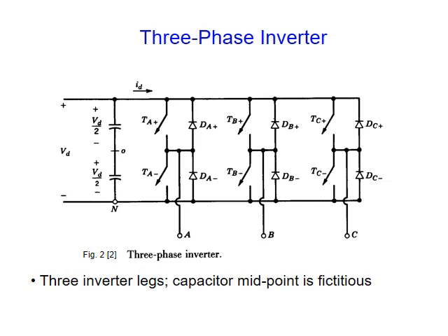Now after we complete single phase, let's go for 3-phase. Before I go for 3-phase, just to make it very simple for you, rather than one leg, we will have another 2 legs. So this is leg A, leg B, leg C. And we control them to make sure that 120 degree phase shift is the phase shift between each of the voltages coming from different legs.